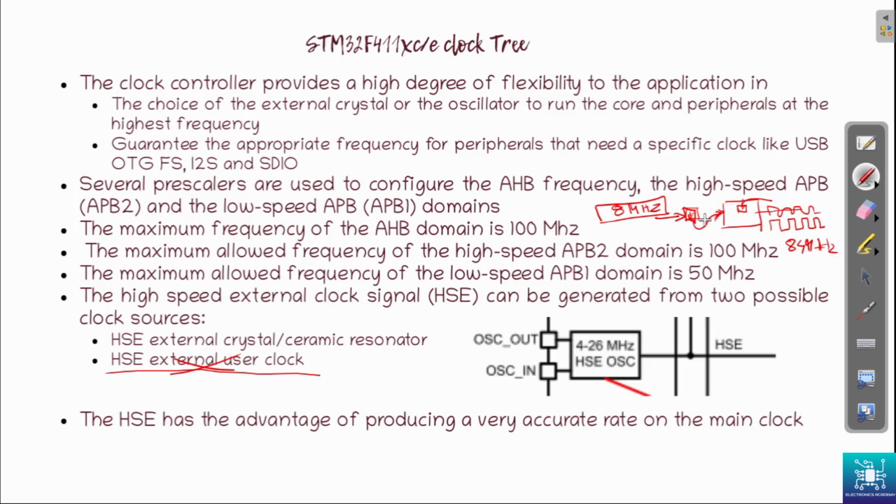So obviously there has to be some circuitry coming in the middle to do that. So the 8 megahertz is going to provide the stable clock, and from there the VCO, or the voltage controlled oscillator, is going to bump it to a higher frequency. But then again, the VCO is not stable. So we'll see all that, how the VCO clock is kept stable through a PLL and things like that.